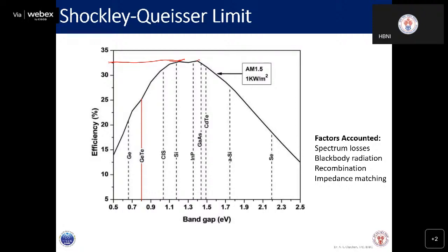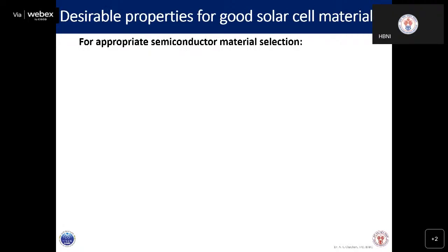And if we want to make a solar cell of germanium using N-type and P-type germanium, then the maximum possible efficiency cannot cross 21%. That is also theoretical, when every other thing is perfect. So this is the Shockley-Queisser limit for the maximum efficiency which can be obtained using a solar cell of these materials.